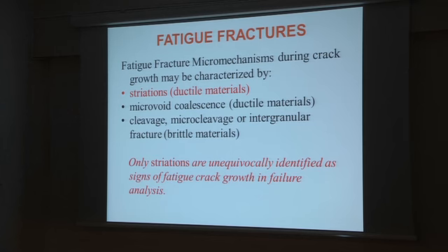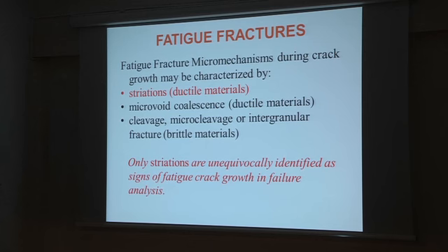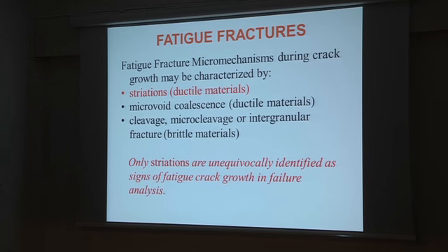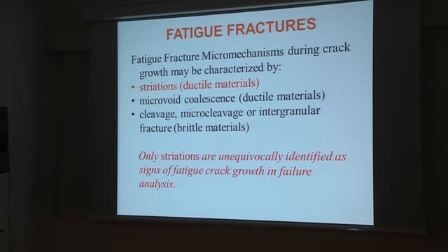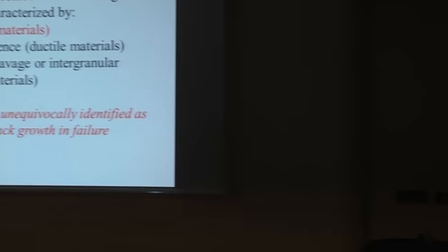So usually the failure analyst is confident to be able to recognize fatigue fractures. Confident. Oh, I will see, and I will tell you if it is fatigue or not. Because he thinks of striations. But instead, he may have fatigue fractures characterized by cleavage, by intergranular, or even microvoid coalescence.